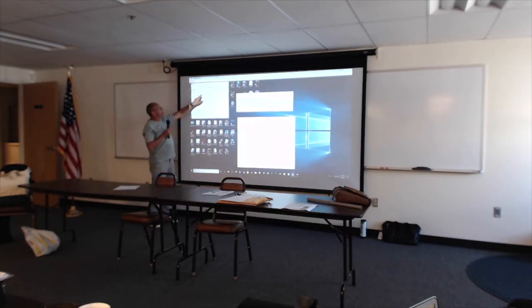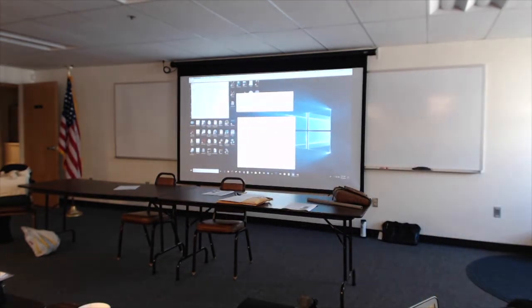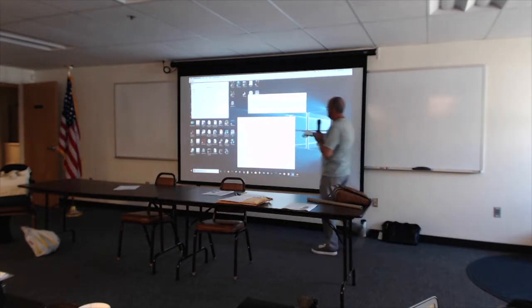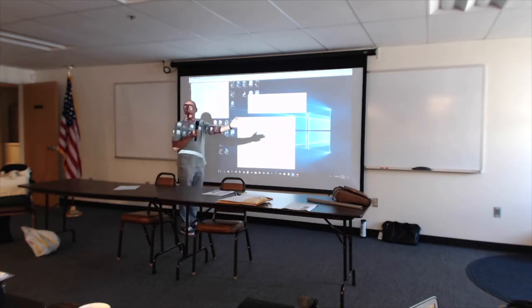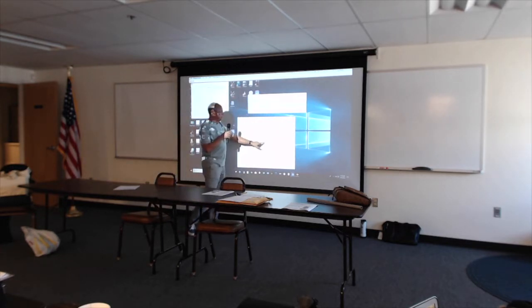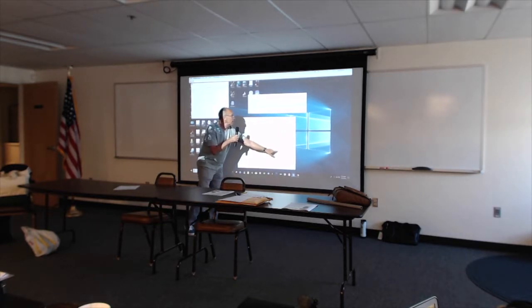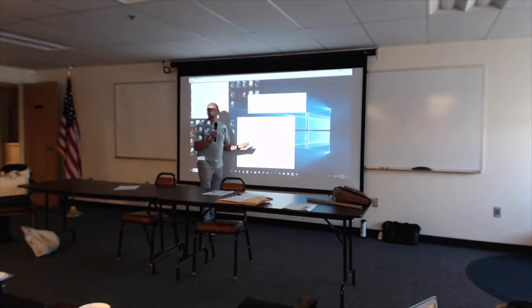The wires entry here says 3 wires, 453 segments. And this is where you specify on an XYZ axis. If our bottom wire is 196 feet, remember positive Y is pointing north, negative Y is pointing south, X is left and right, east and west. Z is the elevation. So we put in some parameters here. Minus 98 is this point right here, and that's for wire number 1. Positive 98 is this point up here, and you add those together, it's 196, right?